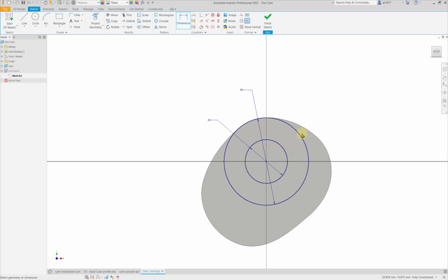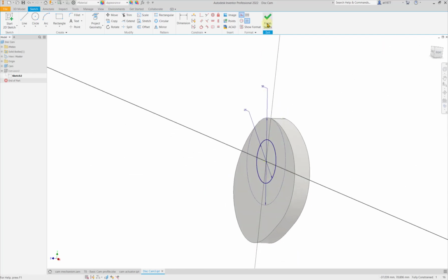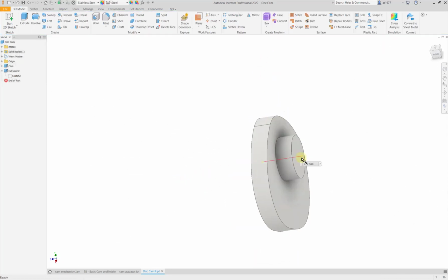Diameter 50. Remember the base circle radius is 25, right? Okay. So notice that my true 3 o'clock position is my 0 degrees, and then the whole cam rotates counterclockwise. So it's correct in this manner. So the hub should be on this side.